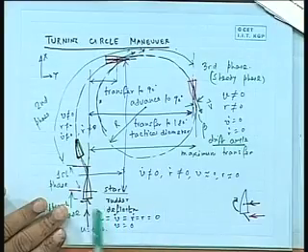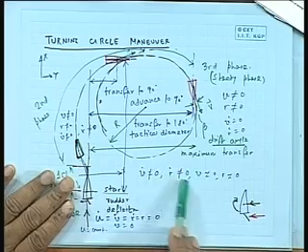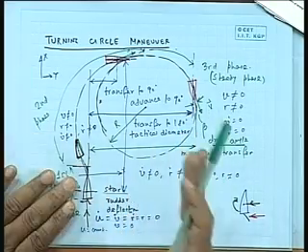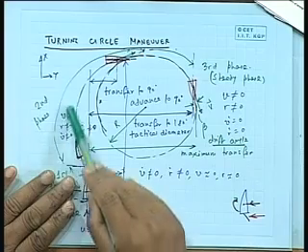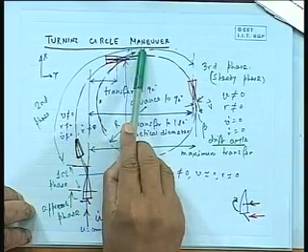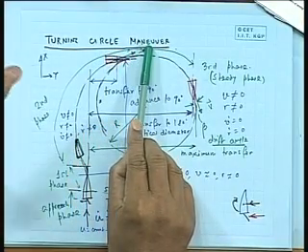You see, what is happening is that in the first phase, the approach phase, just the accelerations have got set up, velocities have not yet set up. The ship has swung here because yaw forces pushed it up here, heading angle has not yet changed. Now the second phase, you will have everything there, and the heading angle slightly begins to change. So there is a continuous change of heading angle up to this point, and there will be some point when the heading angle has become fixed, the accelerations have become fixed, the ship is just turning steadily. If you leave your rudder and you go to sleep, it will keep on turning in a circle. And you are of course not changing the engine.